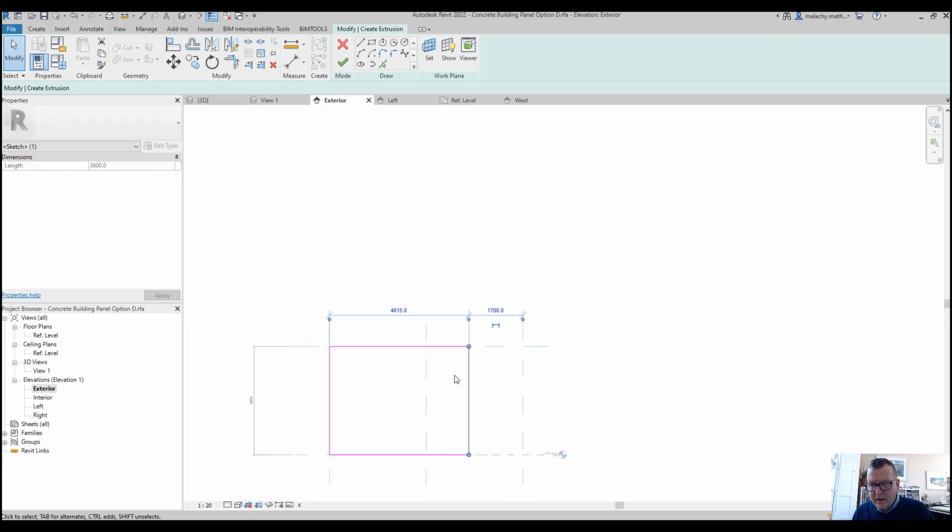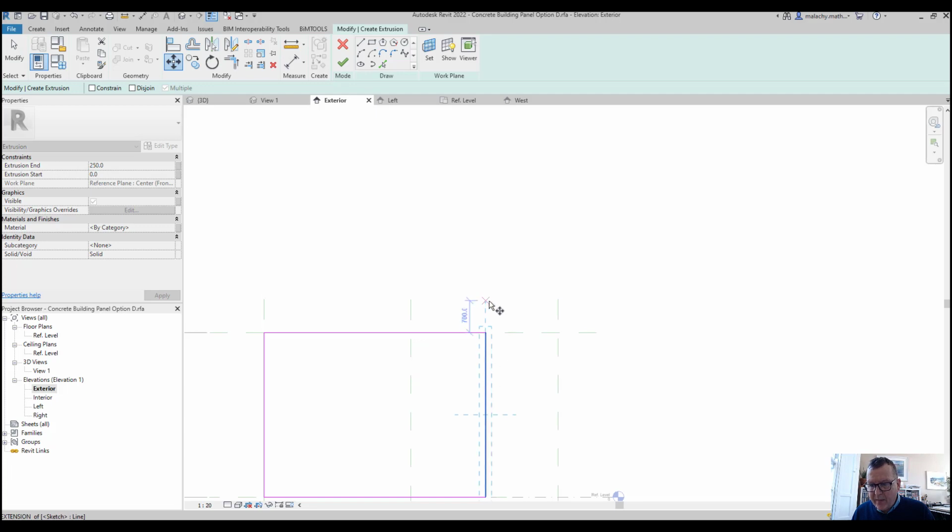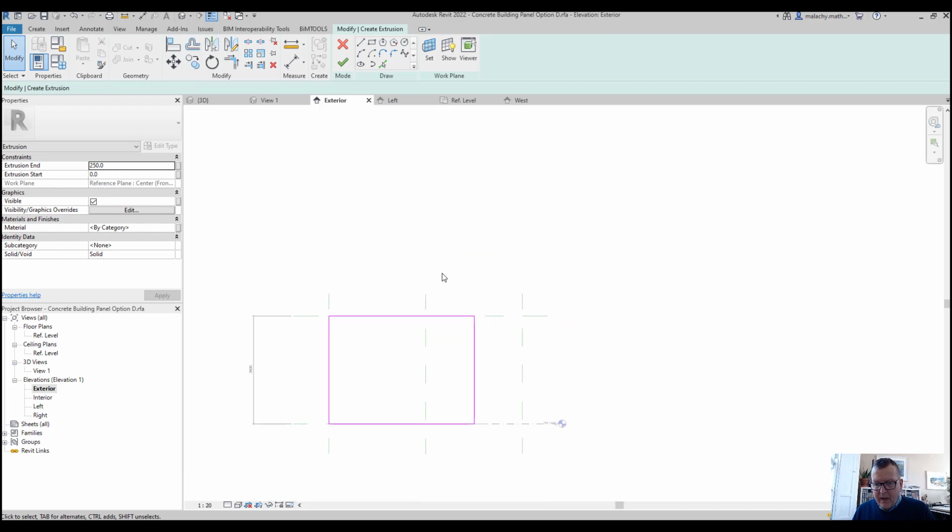Okay, there you go, 415, and what I'll do then is I'll just take that one and I'll move it 15. Now, so there's my 4.8, all right. And now I'm going to go into my offset tool here, and I'm going to offset these 200 onto the inside. Okay, now I want to divide these down the middle, so let's just fillet these bits here.